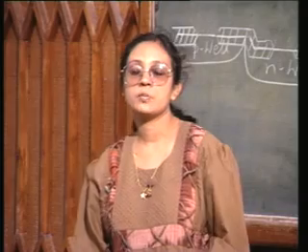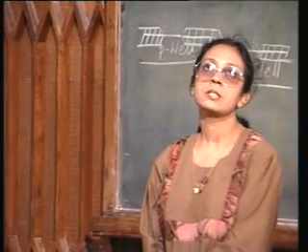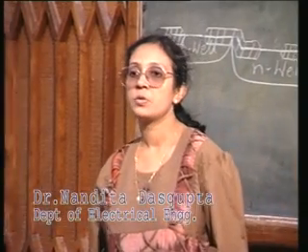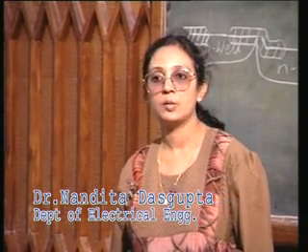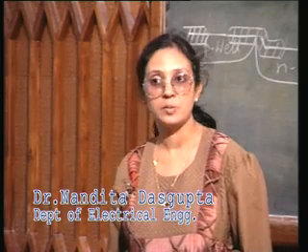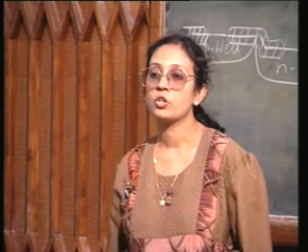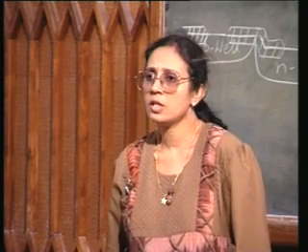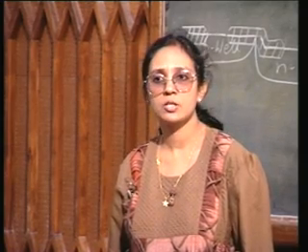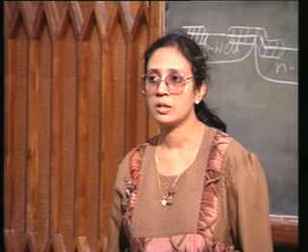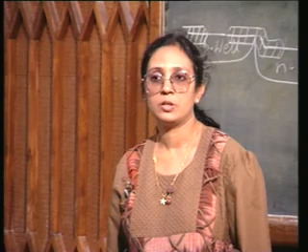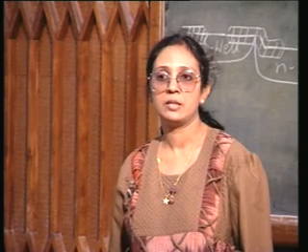So, one possibility will be to use steps analogous to the bipolar junction transistor. You just have a buried N plus as well as a buried P plus, and then on top of that you grow an epitaxial region, and then you just create your wells in that epitaxial region. Make sure that the well is aligned to the buried layers.